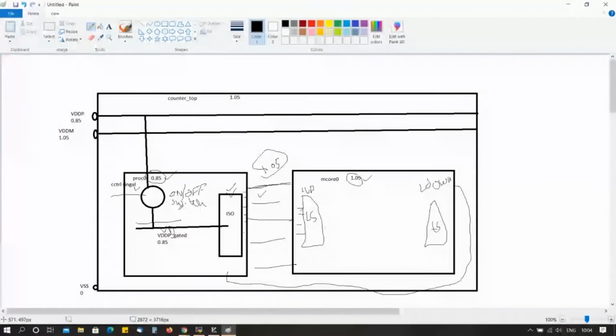Okay, so here in our agenda you are going to create different ports and different nets accordingly, and after that you are going to create power switches, and you are going to define some domains. So this is one power domain, this is another domain, and in one domain you are going to mention a switch, and you are going to create isolation cells to clamp to some value so that your output will not be disturbed. And after that you are going to use some level shifters from another voltage to the particular voltage. Level shifters up or down based on the location. For the inputs you are going to use up shifters, and for outputs it will be down shifters.